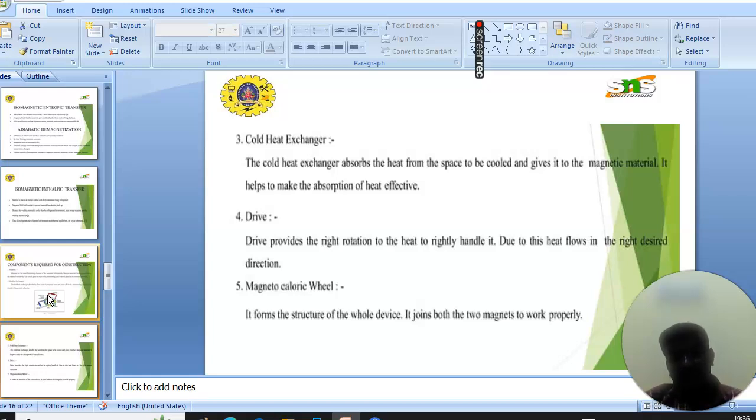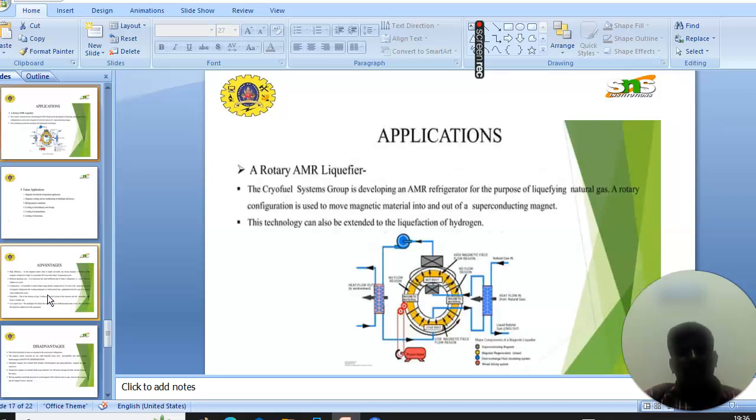The next is isomagnetic enthalpic transfer. In this, the material is placed in thermal contact with the environment being refrigerated. The magnetic field is held constant to prevent the material from heating back up. Because the working material is cooler than the refrigerated environment, heat energy migrates into the working material. Once the refrigerant and refrigerated environment are in thermal equilibrium, the cycle continues.